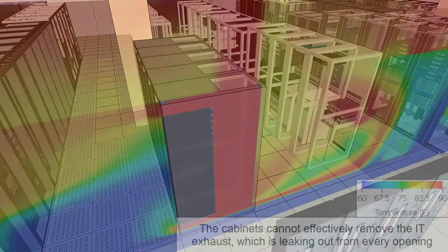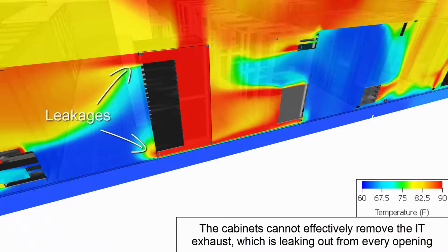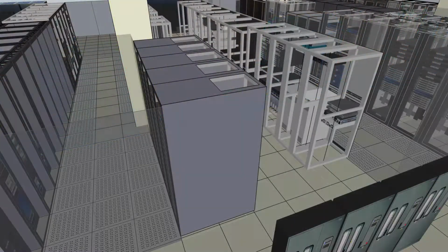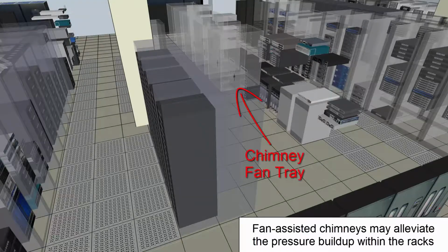In this case, the pressure buildup at the back of the rack is too great, and hot air is leaking out of gaps in the mounting rail back into the IT equipment. It's possible that installing fan-assisted chimneys could help reduce the pressure buildup in the racks and more effectively remove IT exhaust air.